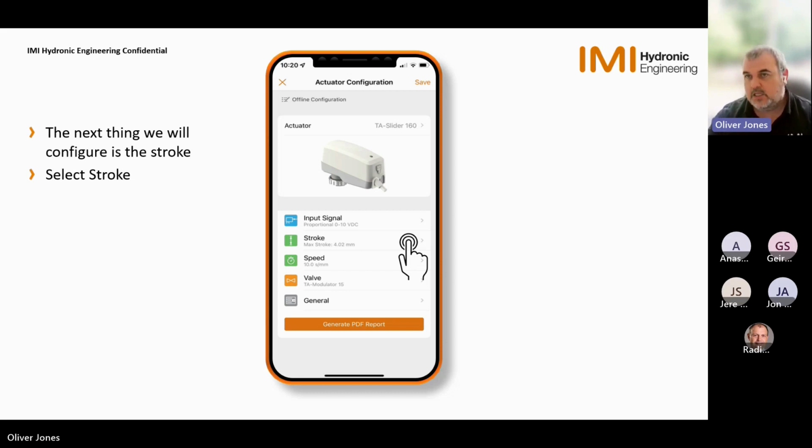So if you want a smaller flow rate than 0.133, which is out of the box at 10, we'll give you a setting. So if it's setting 5, you move the valve to setting 5. There are some ways of doing that. Obviously, it's a very small hand wheel, and sometimes within the positions that these valves are set, it's not exactly the easiest thing to physically look and see where those settings are without torches and mirrors.